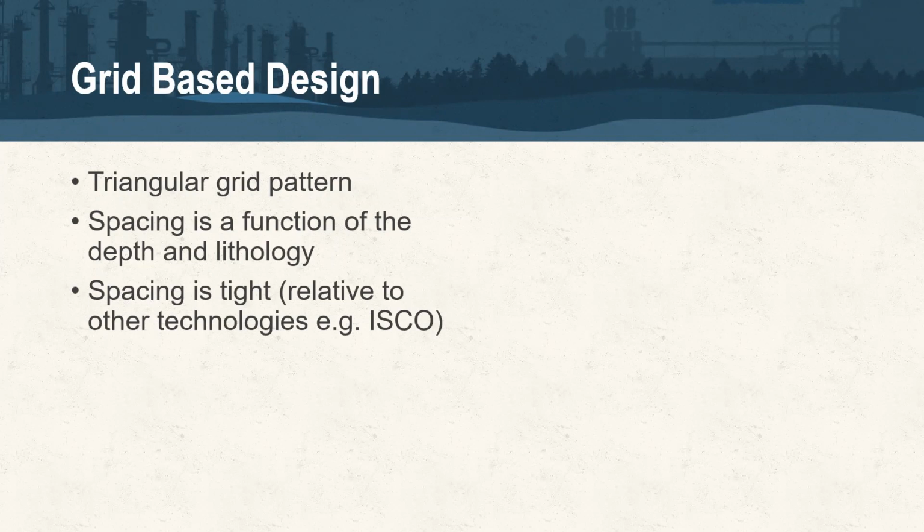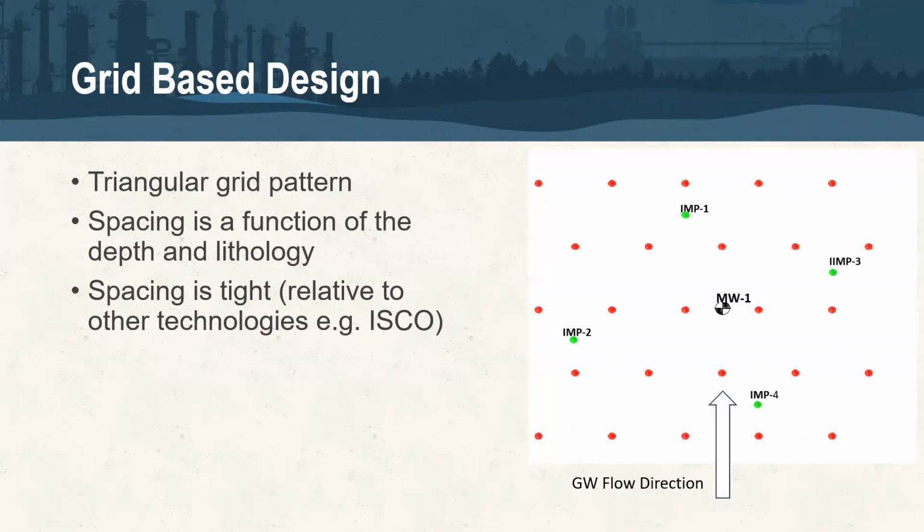So we like to think of this through the injection design process as trying to essentially affect a known carrier volume with pounds of a product in it, Fluoro-Sorb, across a specific interval of the site. And when we make those succinct shots within that specific interval, we get the distribution that we know we've got contact within that zone. So that's a long way of saying we're trying to dial this in. When we turn that pump on and off, we know exactly how much we put in situ and that it stayed in a relatively planar feature within the subsurface, which is our target, right? That offset interleaving pattern. Just an example of a grid-based setup in a well field.